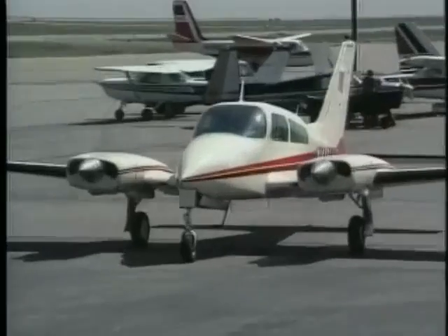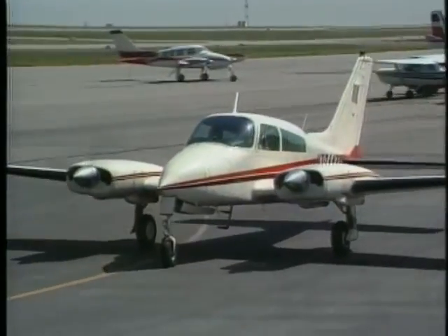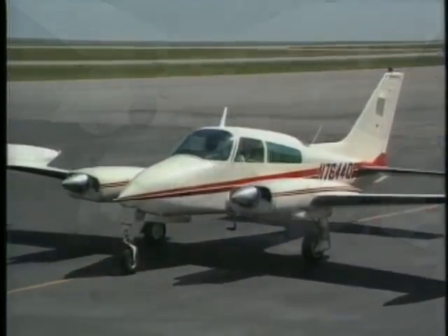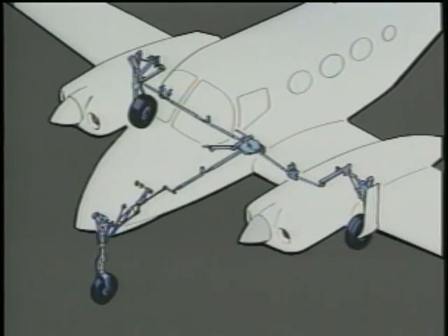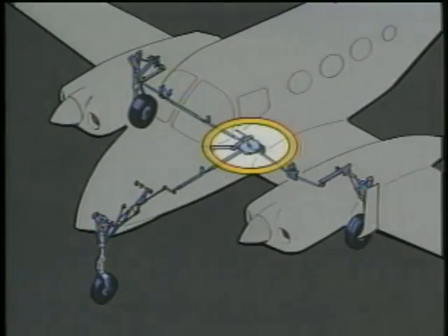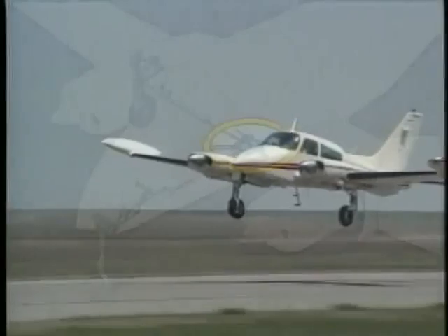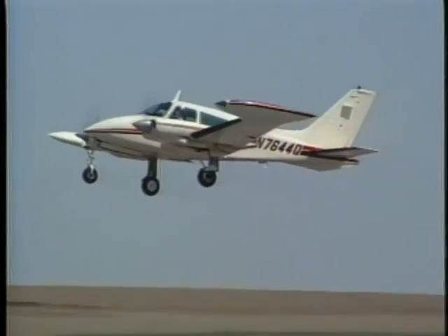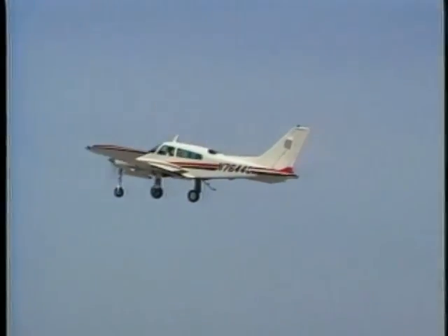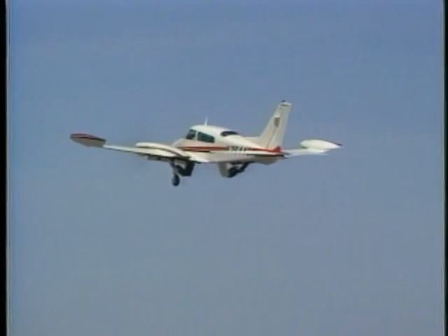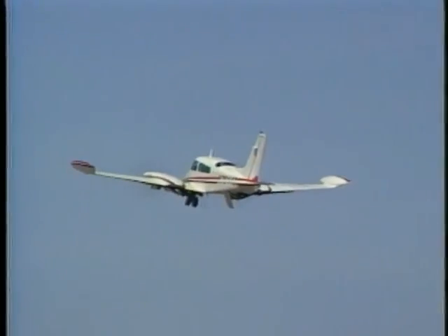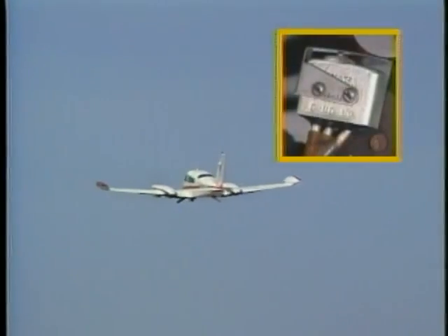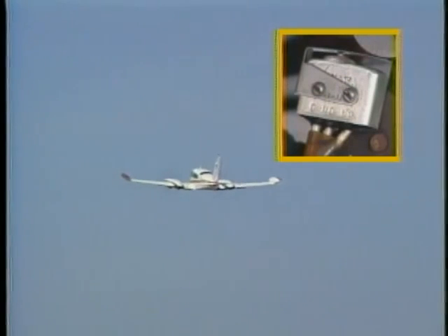The first type of system we'll examine in detail is the electrical gear system. In this particular aircraft, each landing gear is mechanically linked to a gearbox, which is located in the fuselage just behind the pilot's seat. By moving the gear handle, power is supplied to an electric motor, which drives the gear toward the selected position. The motor will keep running until the up or down limit switch on the gearbox disconnects the electrical power to the landing gear motor.